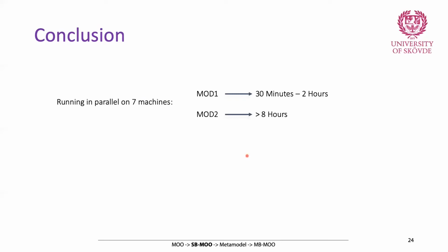If you remember the elements I showed you in the previous slides, you have to select very small elements. Having small elements increases the number of elements, and increasing the number of elements increases the computational time. Each simulation for mode 1 in peel took around 30 minutes to 2 hours, and each simulation for mode 2 took 8 hours.